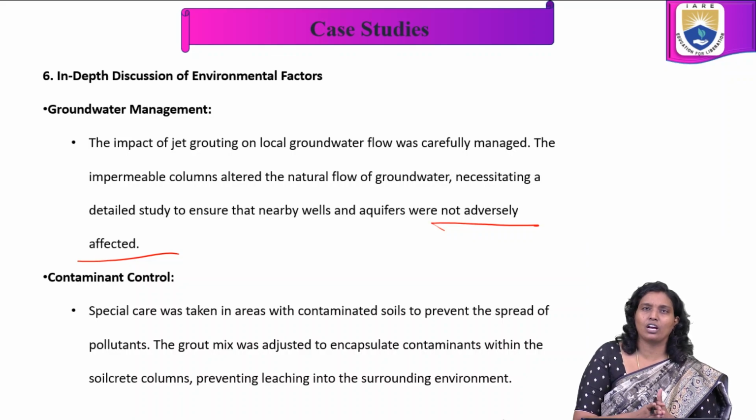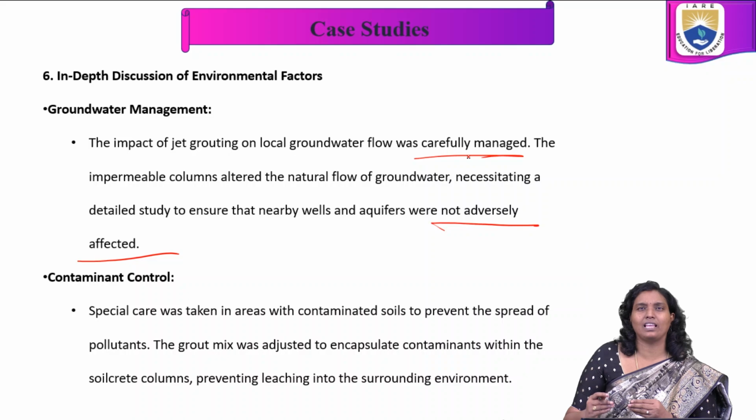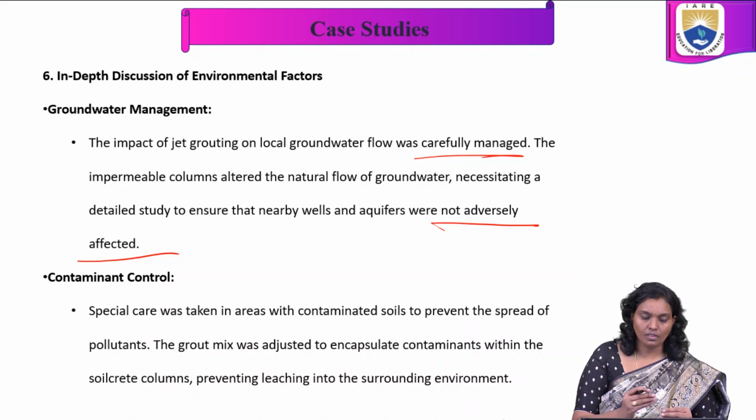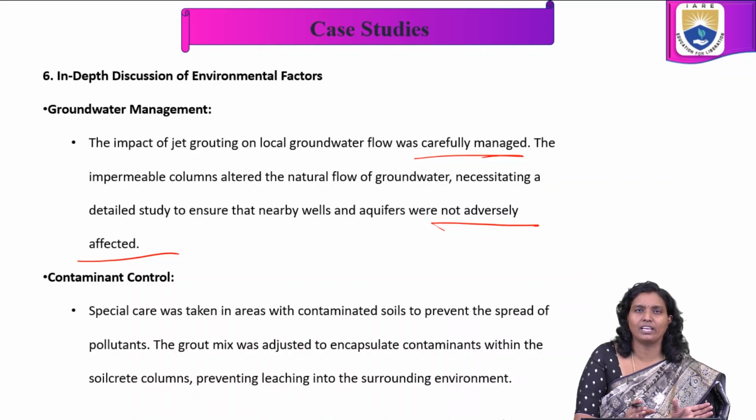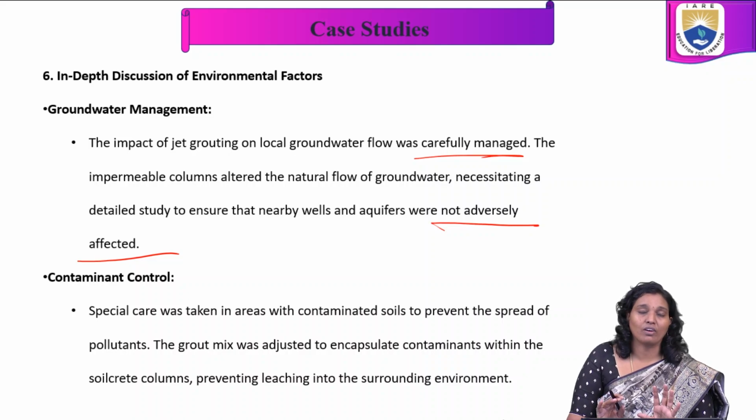The impact of jet grouting on local groundwater flow was very carefully managed. Once we understand which columns we are going to choose and how they alter the natural flow of groundwater, we do detailed studies to ensure the nearby wells and aquifers are safe. So this is also one of the environmental factors which we have to consider.